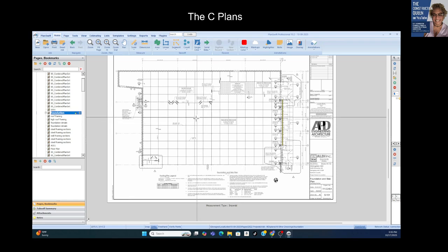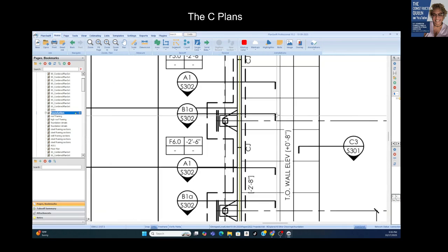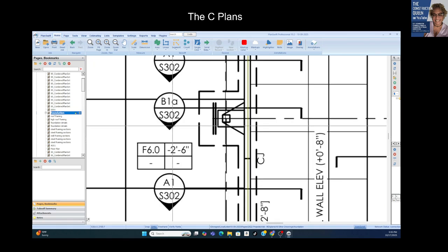Okay, so when we look at the foundation plan again, a foundation is three component parts: the slab on grade, the continuous footer, and then, in some cases, we're going to have column pads, which is represented by here. So how do they tell us how they represent the column pad? It's just a square. Imagine in a parking lot, right? There's always some square piece of concrete that maybe something is sitting on, maybe the light pole or whatever.